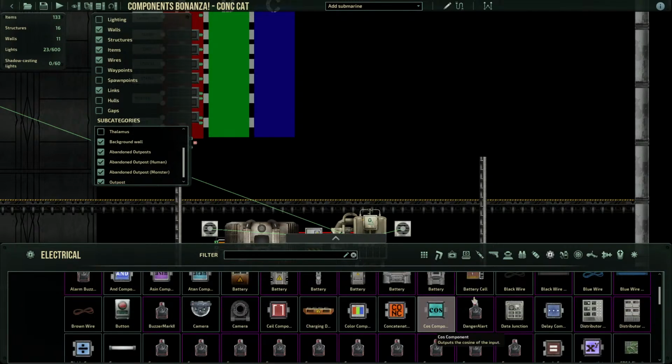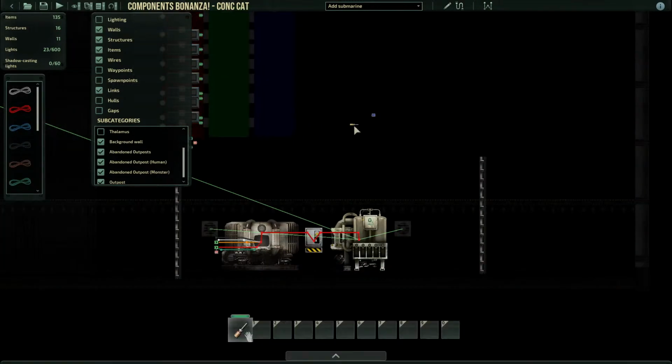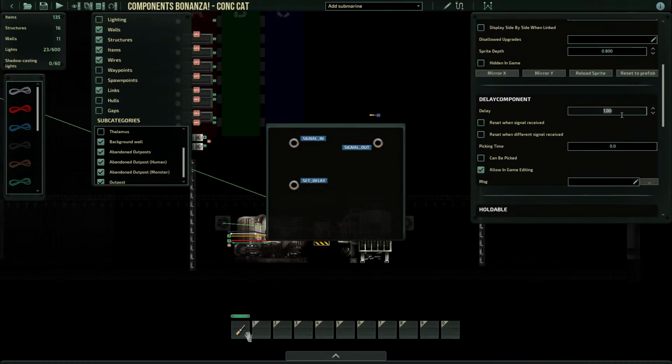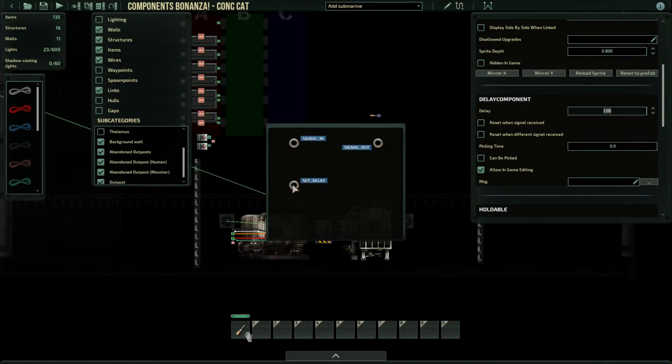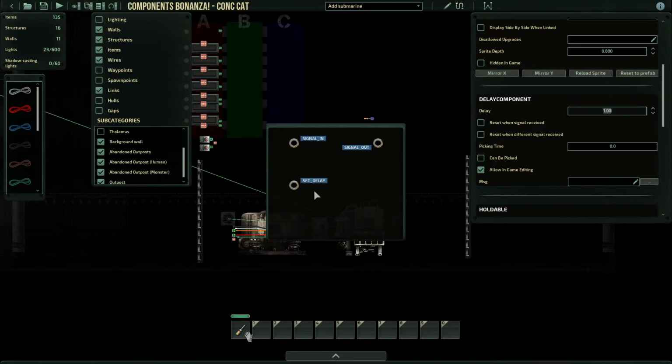Okay, cosine, we've already talked about. Delay. Okay. Delay is easy peasy. Whatever signal comes in the signal input is passed through to the signal output after whatever delay you've set here in seconds. You can define the delay dynamically with the set delay box. If a 0 or a string arrives at the signal set delay input, that sets the delay to 0, and you get an immediate output from whatever it goes from here to here.